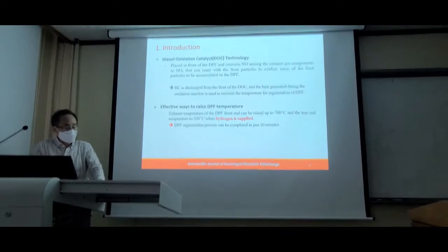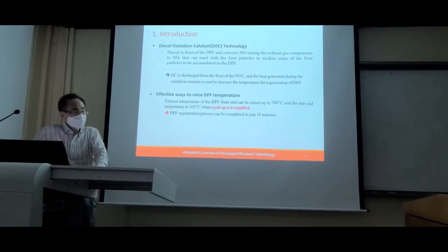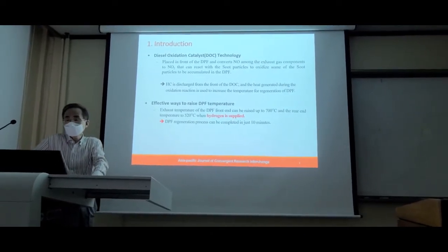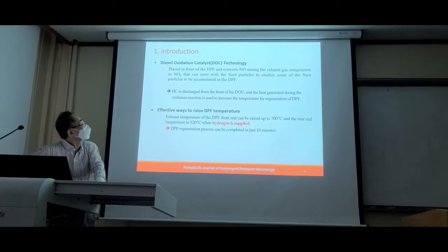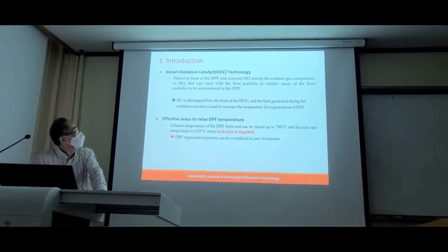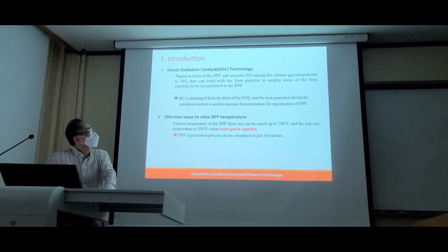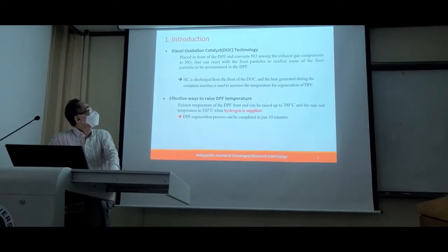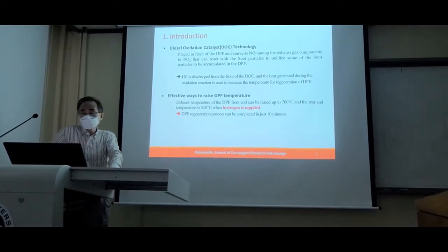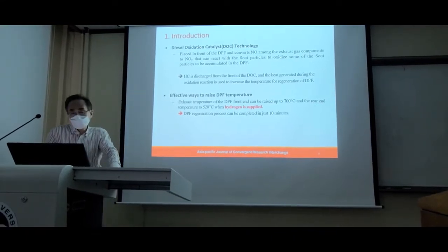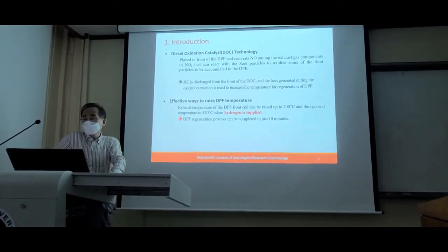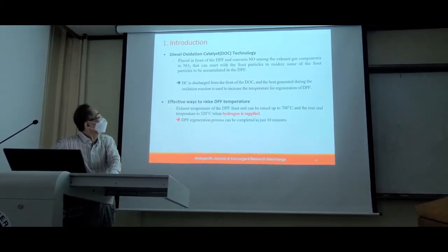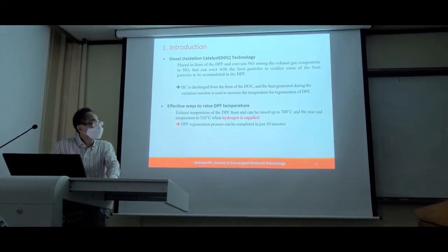And another technology we can also mention in this is called DOC, the diesel oxidation catalyst technology. Placed in front of DPF, it converts NO along the exhaust gas component to NO2, which can react with the soot particles to oxidize some of the soot particles accumulated in the DPF.